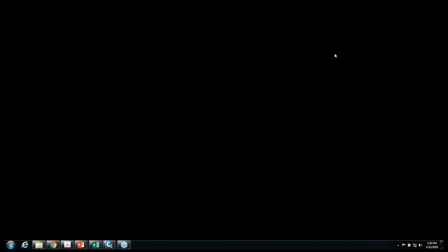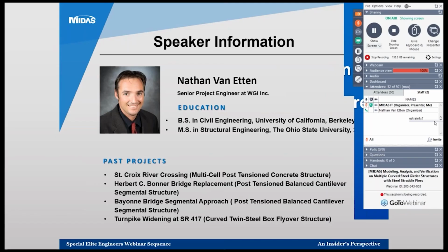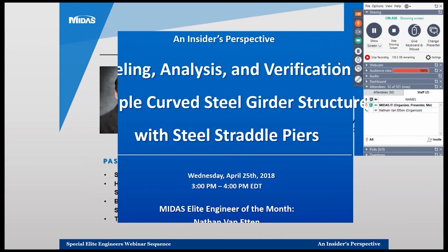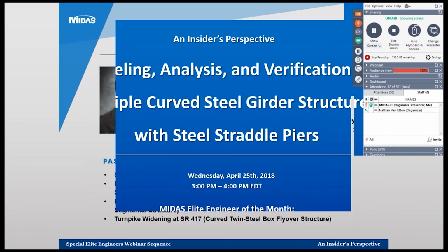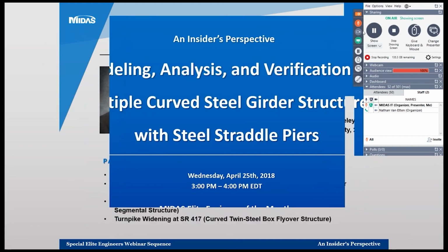If we were to add an additional double dipping of the stiffnesses between those two, we would not have such good similarities between the two analysis software in between the support conditions. Obviously, where we use the springs, we'd have very similar results, but in between there, we wouldn't see such a good alignment. So there is not a double dipping of the deck stiffness.